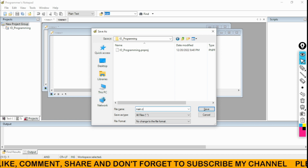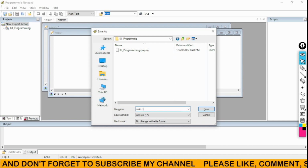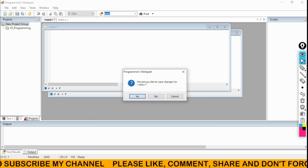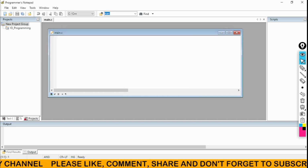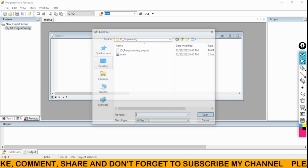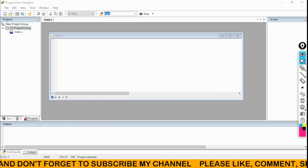Keep in mind, this is very important because while making the make file, this name is important. By default the make file name has main, so we'll take the file name to be main.c. I'll save it. This is another text file, but main.c. The next step is to add that main.c file to your project. So I'm adding it. And the next part is we have to create the make file.